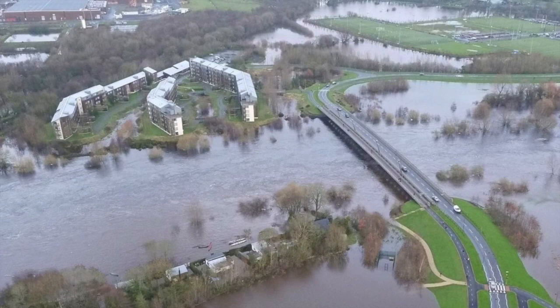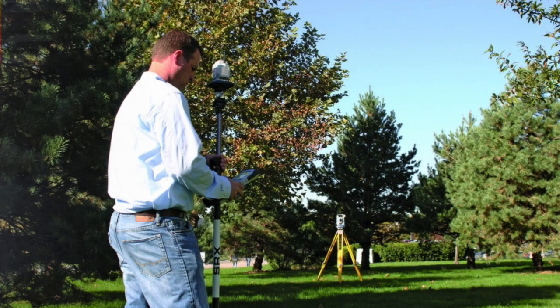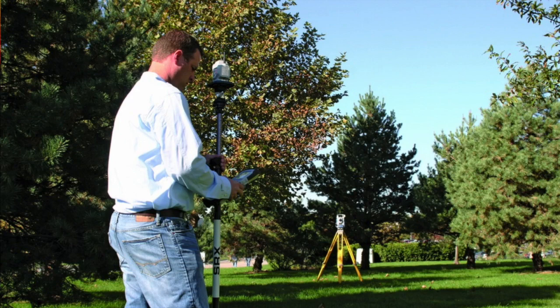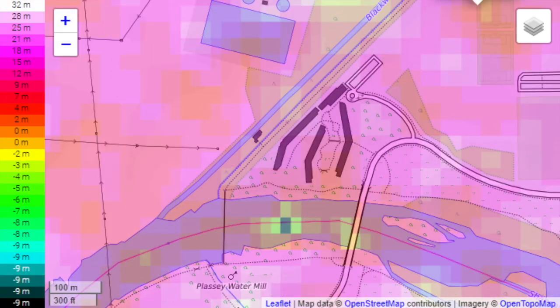Finding the correct site levels and flood levels is vital to the success of the dam. We use known levels on site where possible. If there is no known level on site, we can use online facilities like CFRAMS or the Office of Public Works topography maps. To find the height of flood to be prevented against, we use flood level data from reliable sources such as Met Éireann or the OPW flood maps.